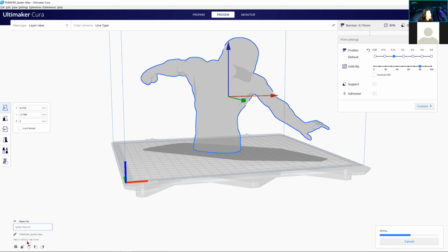But yeah. Cura is, I think, probably one of the more user-friendly slicers that I've used. The Prusa slicer I mentioned earlier is a little more difficult to customize. Like removing supports and stuff like that, it's a little hard to tell where everything is. But I think Cura is a lot better, and you can definitely play around with more of the settings, like changing temperature, changing the support type, which is nice. Alrighty, I'll wait for this to finish slicing. And then I'll go over some more of the support customization stuff.